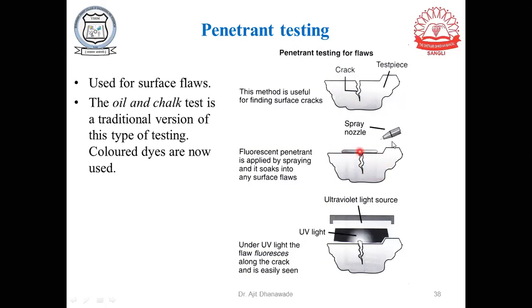Now you can use some spray or nozzle to make sure that if there is any crack, the dye will go inside the crack. After this, you just wipe out the dye from the surface, but whatever dye has gone inside the crack will remain there only.